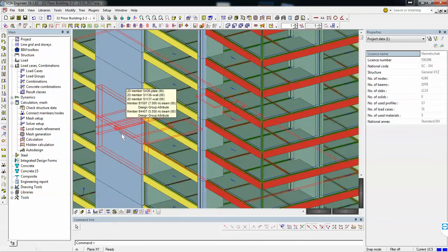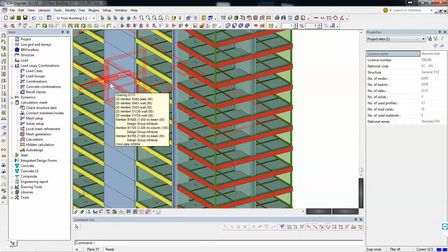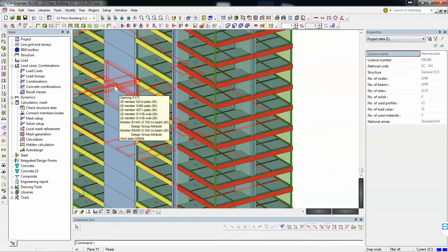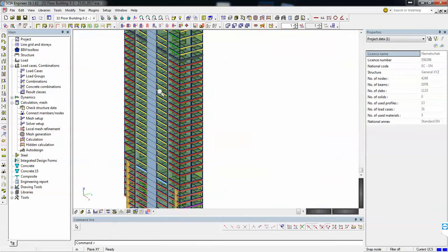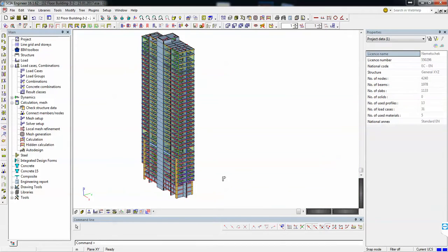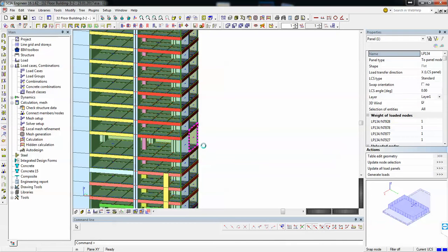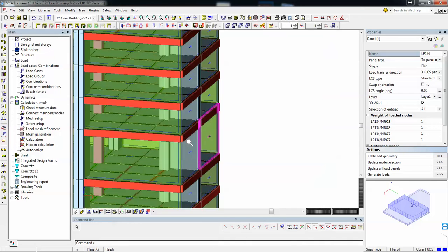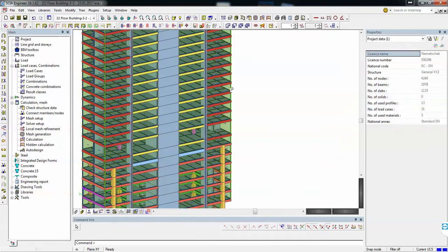On this side of the shear wall, you will get a uniform distribution within the wall that will act on the nodes. So basically in the end you will get a similar thing, but from a settings point of view, they are quite different. So it's okay the way you set the panel to nodes, so it will only get concentrated force in nodes, and we can see them once we manage to generate the 3D wall.